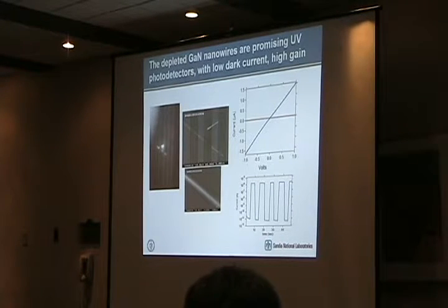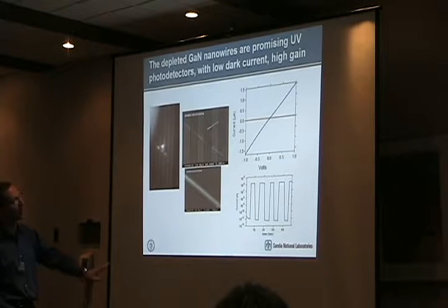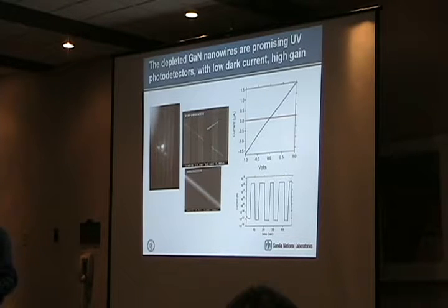Oh, this is the slide. So here you're seeing a nanowire that's fully depleted, but when we shine essentially nanowatts of very low UV power on this nanowire, we see the current. This is a single nanowire, and we packaged it because there's some people at San Diego. This is one of the things that people are interested in, photodetectors, particularly if they have low dark current, because you'd like to get away from things like photomultiplier tubes.